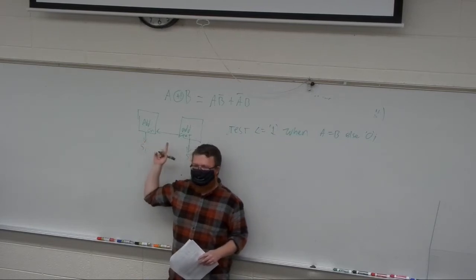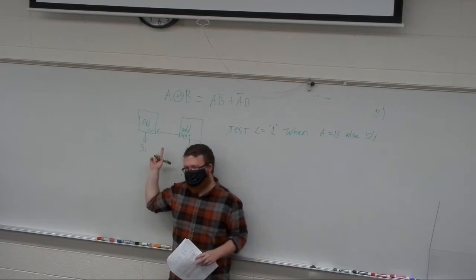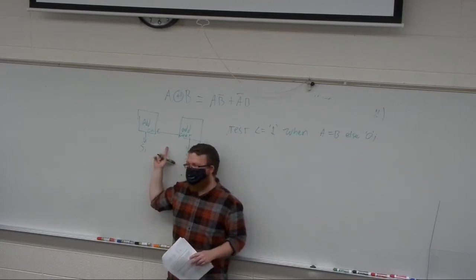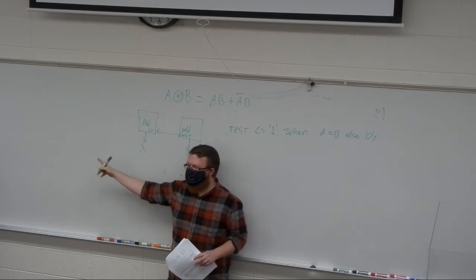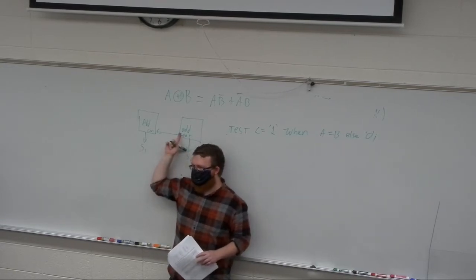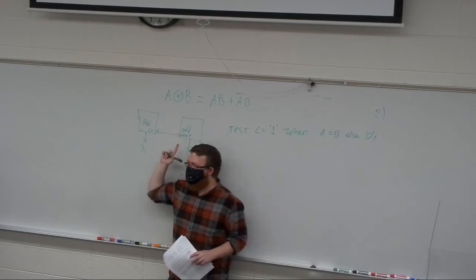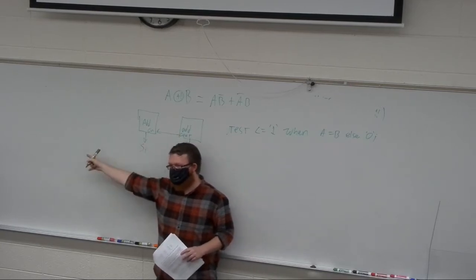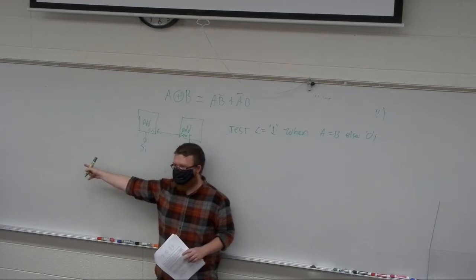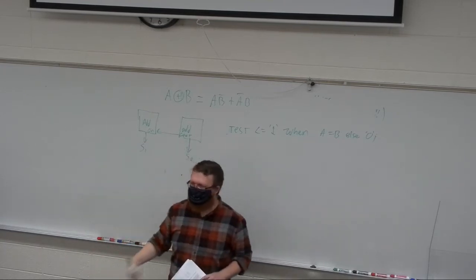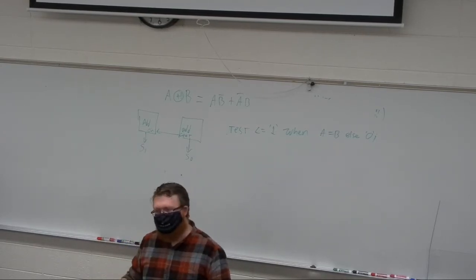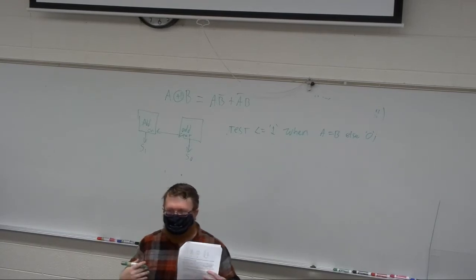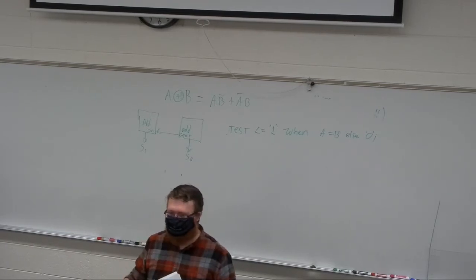If each of these has 2 gate delays in it, which is reasonable, 2 or 3, then I would need 2 times 32 gate delays in order to do this addition, right? So this is pretty size optimal because each of these blocks is not very big. It's just a couple of gates. But it takes a long time to ripple down to a 32-bit adder. We don't want to wait that long. Sometimes we want to add things together quickly. So what we're going to talk about starting now is something called a look-ahead adder or a fast adder.